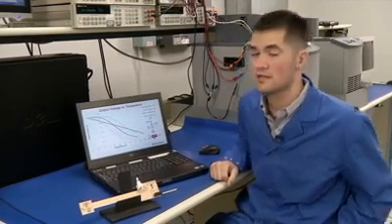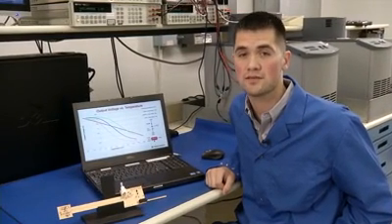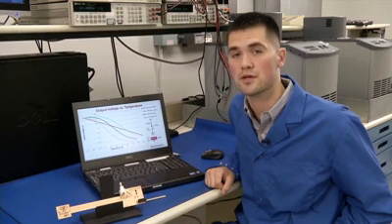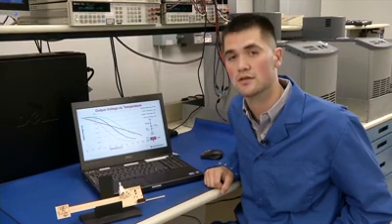Another thing to note is that analog temp sensors do not require the additional components, such as the resistive network that is required by the NTC thermistor. This is important because those additional components add to the cost and the footprint of the overall temperature sensing solution.